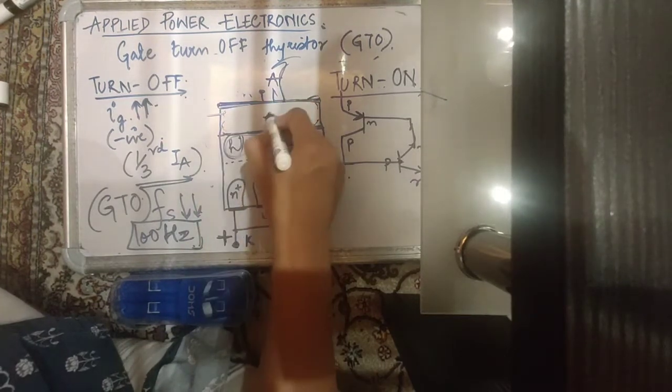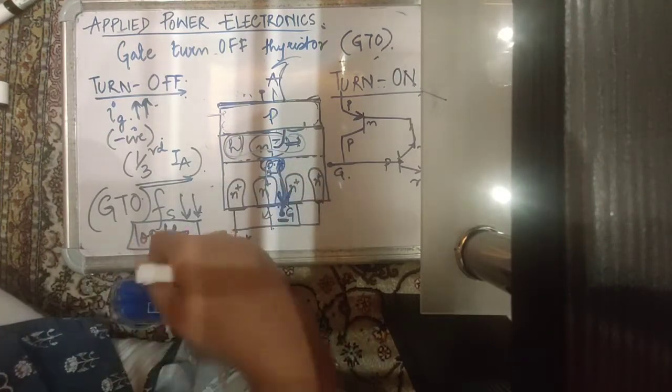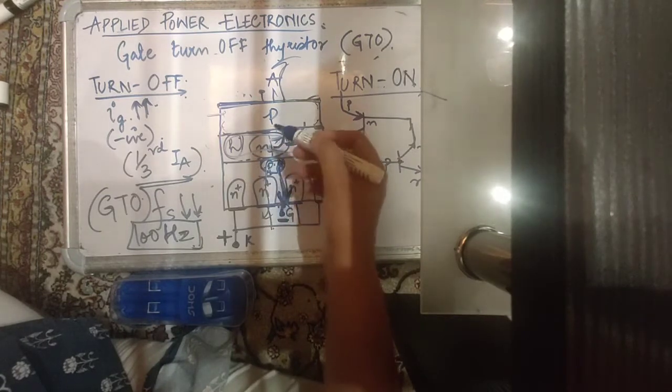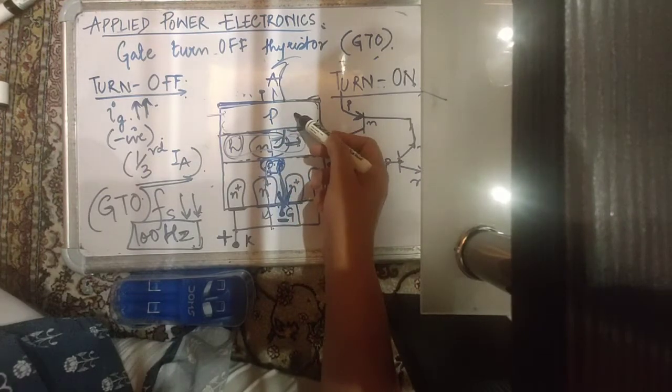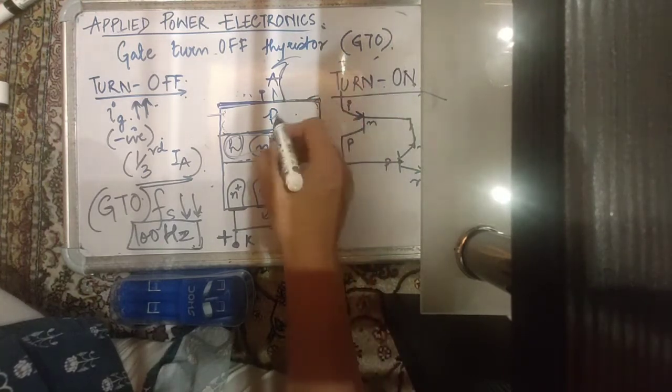अब अगर ये नहीं होता, let's talk about a thyristor. जो simple thyristor था, वहाँ पे आपके n minus region के दोनों साइड से p regions थे जहाँ पे holes की concentration बहुत ज़्यादा थी. तो ऑब्वियसली holes will never move from, any carrier will never move from low concentration to high concentration, but they will move from high concentration to low concentration. That's the essence of the diffusion process.